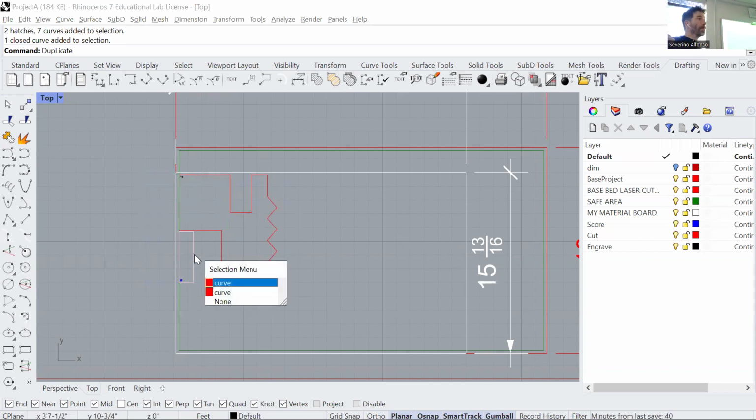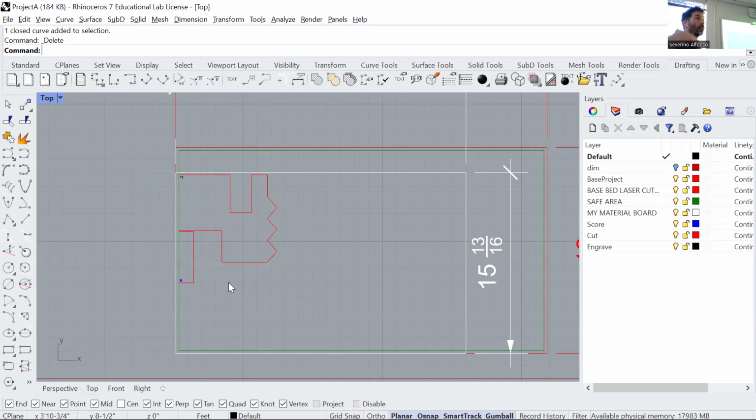And if that pops up too, you know there are two things in the same place, and that's when you select one of the two and you delete. So try to avoid duplicates. That's true. The make2D is what eliminates the duplicates. In AutoCAD, you have the kill duplicate, and I think in Illustrator, you're going to have to go one by one as well, being careful with that.